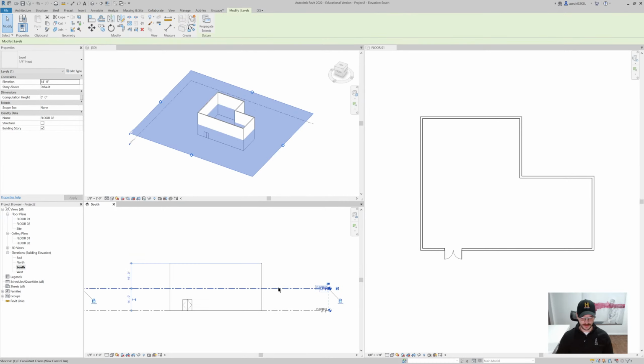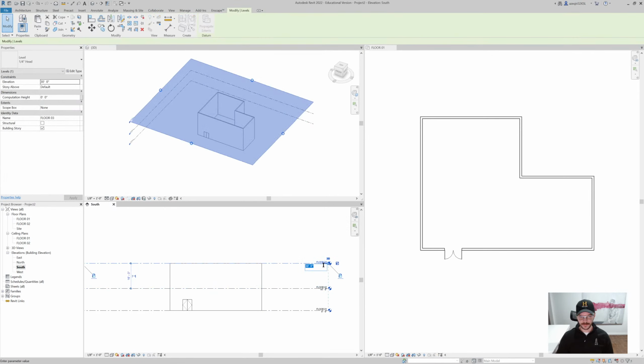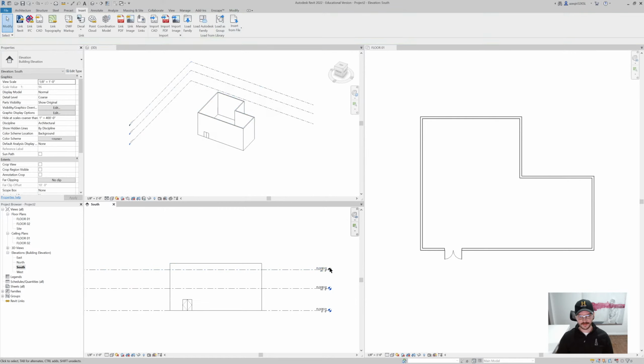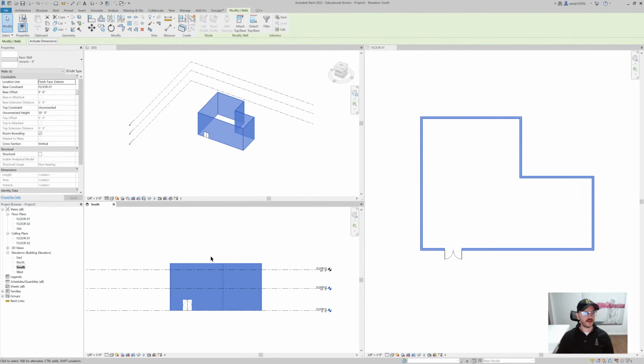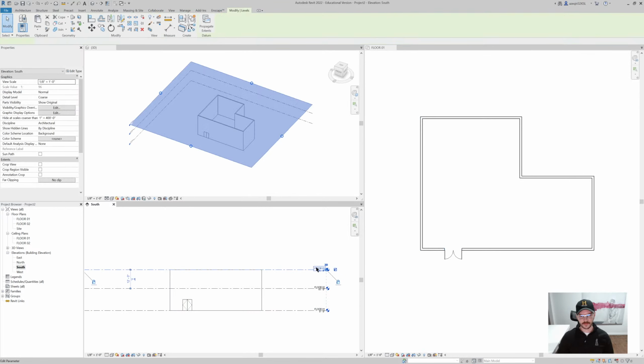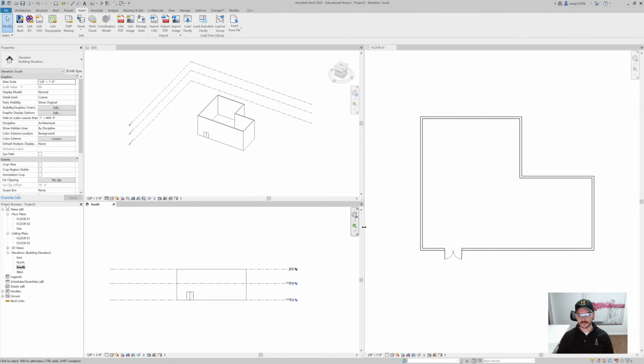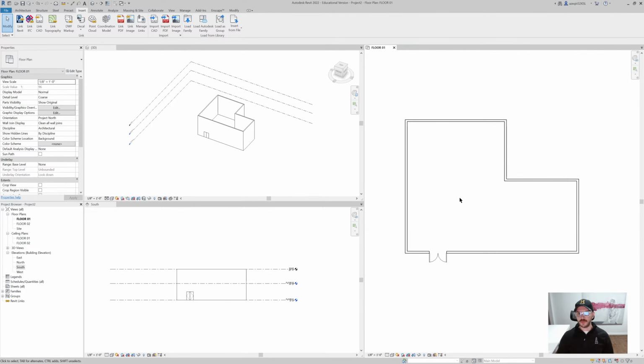So we have a floor 2, let's copy that, we can set that to wherever right now. Let's do 12. Revit can do math for you, so if you're feeling lazy, you can do just 12 plus 14. No, I know how to do that in my head, but no need. Let's change this to roof. Okay. All right. So we're back in our floor plan.